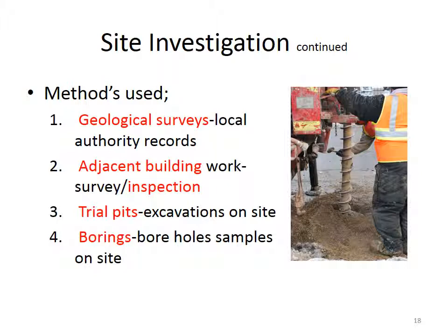We can use trial pits. These are excavations on site. These are for larger sites maybe, or if you're not too sure about what kind of subsoil we have. We can use borings also. This would be maybe if we're on ground that's going to have to be piled. In other words, we're going to have to send foundations down quite deep. So these are borehole samples on site.